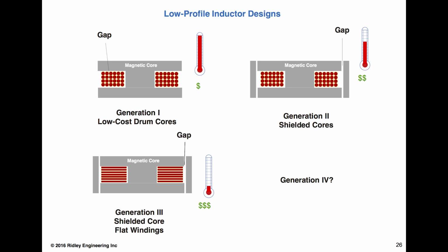But the important thing for all the high-frequency switches nowadays, ZVS won the battle of which one should you do, zero current or zero voltage. And what you mean by ZVS is that when the main device turns on, its voltage is already zero. It's that turn-on loss that really gets you. And the turn-off loss is ameliorated by putting a cap across the device. So it's zero current and zero voltage at turn-on, and then it's zero voltage at turn-off because of the cap that can be added.